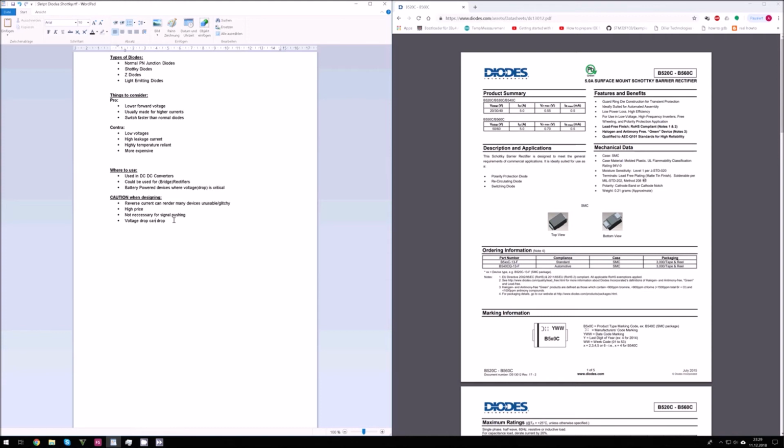If the current draw of the device at 2.7 volts is low, the voltage will increase to almost 3 volts. Take that into account. Many devices can go to standby and draw a few microamps, and the Schottky diode will increase the voltage at the output of the 2.7 volt device higher and higher. It could potentially damage the device or render it unusable. So take into account that the voltage drop can get close to 0, and thereby make many things not work the way you intended.